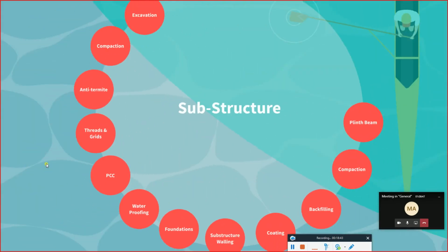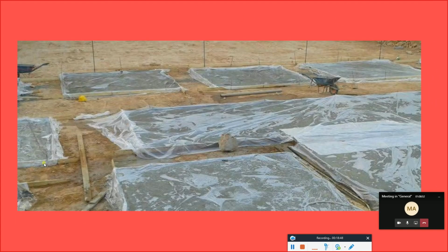Going to the next step, this is what we call the waterproofing or the membrane. If you remember the previous picture, we have done the waterproofing. After doing the waterproofing, we are going to have the concreting. So this is an example of waterproofing here. Although it's not that clear, this might as well be curing sheets.